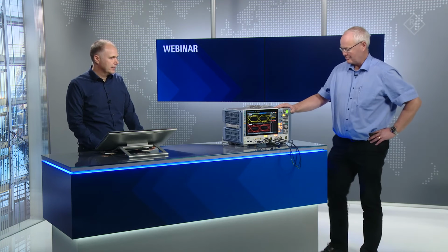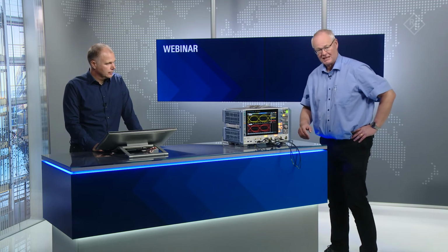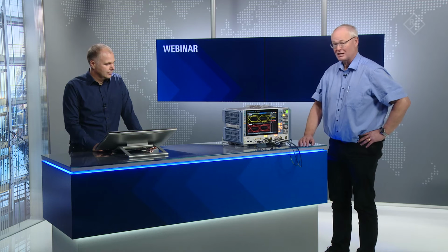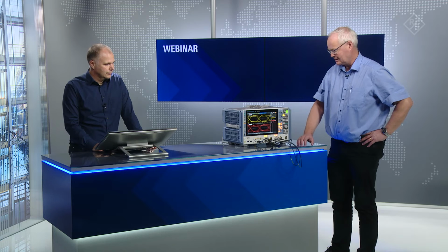So let's have a look at the setup we have provided here. I'm able to sacrifice my USB demo stick. I have a breakout board that separates the transmit lines, which I have connected to channel 3 and channel 1. I provide the USB power to the USB memory stick.